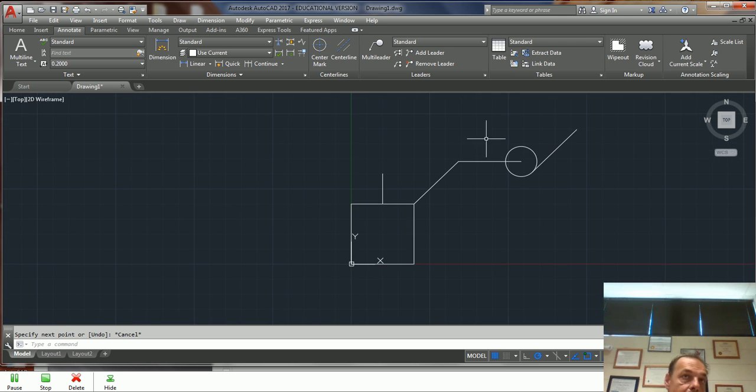Now I want to go back this direction. I'm going to go L, enter, snap here. I'm going to do at 10, tab over to my angle, and what is that angle this way? That's 180, enter. All right, so I went that way. Now, you can also do negatives. If I do L, enter, and I want to do a distance, this time I'm going to go at, I'm going to go negative 10, all right, with an angle of, let's say, 270, enter. Oh, I can't do, see, sorry, in the direct distance mode, you have to type 10 and do, oops, go L again, at 10, tab over 270, boom, that takes me down.